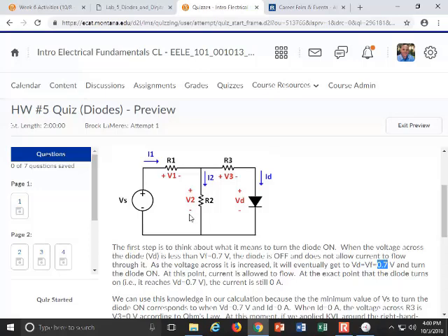Yes. Now guess what? You can figure out this current doesn't come from here, it comes from over here. So now I2 is this loop, and I1 is equal to I2. You can now solve for the voltage V1. You then take V1 plus V2, and that is the voltage at which it turns on. Look at how crazy that was.